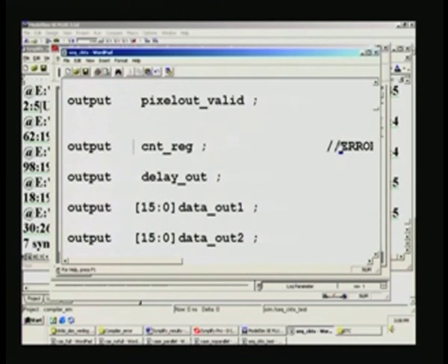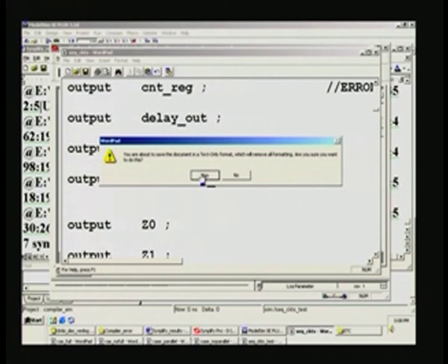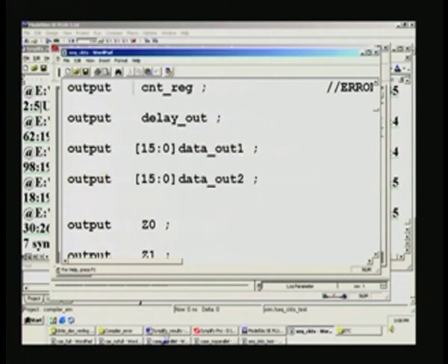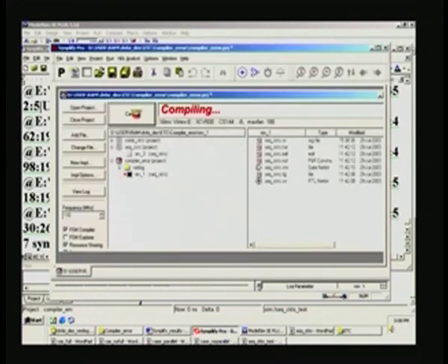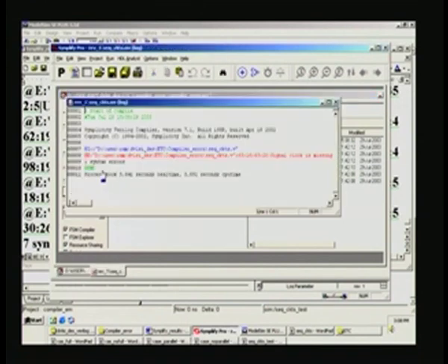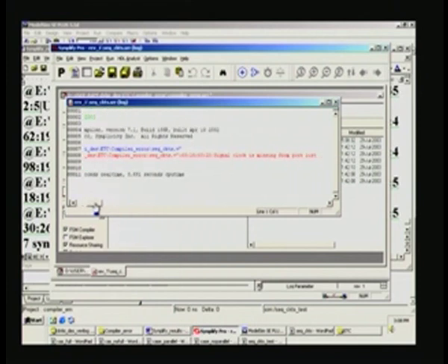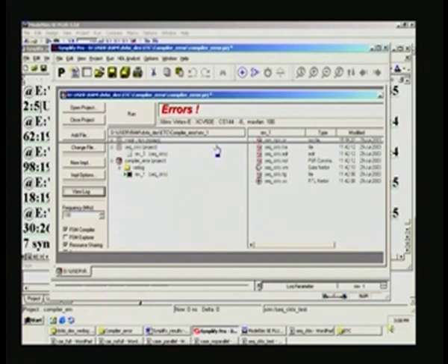So just an indicator that we have created the error here, just putting there. So now let us simplify and run that. It is reporting error. Signal clock is missing from port list. Is that the error that we had? That is not the one, right? So let us find out why it is.